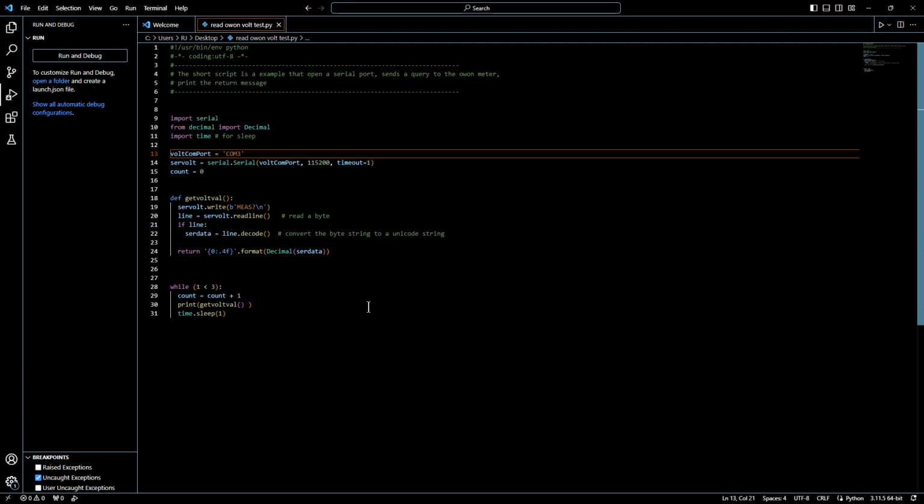You're going to have to plug your meter in and power it on, although I think when it's powered, it still opens a COM port on this particular meter if there's power to it. Go to your computer and find out what virtual COM port it created. It's going to create a COM3, a COM4, 5, 6. You've got to find which one. If you can't tell, unplug the USB and plug it back in on the meter and watch which one comes and goes on your Windows machine.